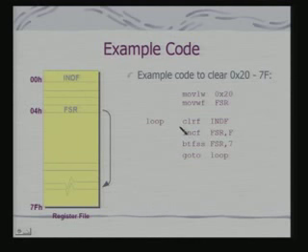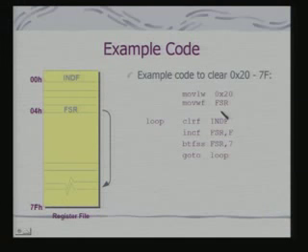In fact, what you have seen is, interestingly, an application where indirect addressing is really required, because here you are changing the content of a memory location in a loop. So, you cannot use the address directly as part of the instruction, because this address has to be constantly changed. At each step the address has to be incremented, and as we increment the address, we have to go back and clear the content. So, this is a simple usage of indirect addressing and how it is exactly used in PIC.